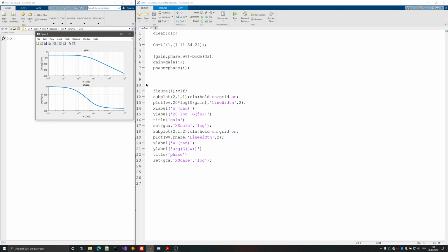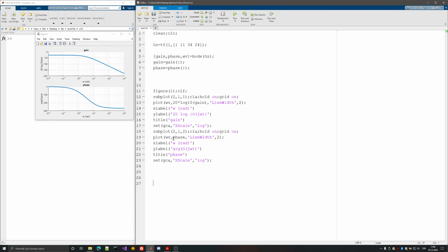It is interesting to be able to just use the bode function so that it will give us the data and we will plot ourselves. Now this has a slight advantage and a disadvantage. The advantage is that I will use this plot and I will look for some points. I will be searching for some points, and I can mark those points programmatically, so I like that way. You might prefer the Bode plot that is generated by the control system toolbox and use that.